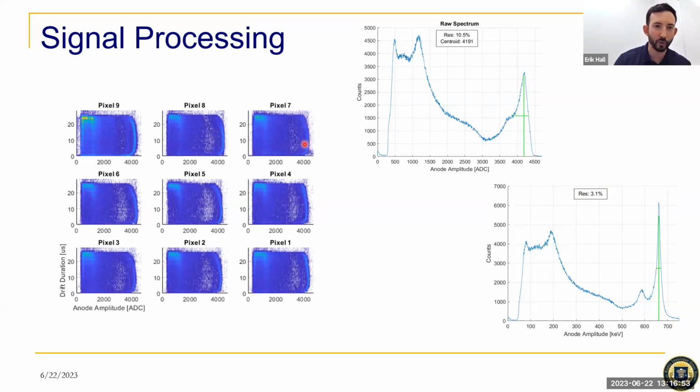In this crystal, there's probably a little bit of trapping, which is one factor that will change the photo peak energy recorded at each depth. But there's also maybe a material non-uniformity that causes a different gain in each pixel, or your readout electronics. We have a separate preamplifier attached to each of these pixels, which I'll go into in a later slide. And each of those preamplifiers will have some slightly different manufactured gain. So that's another thing that we need to correct for when we do depth correction.